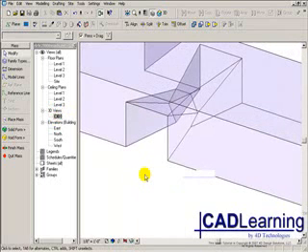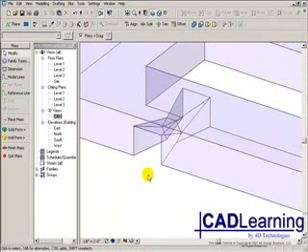Now the one problem with the blend tool is that you can only have 2 profiles. You have a top and a base. So to create this type of blend, you actually have to use 2 blends. One for the first portion, one for the second portion. And if you needed to go